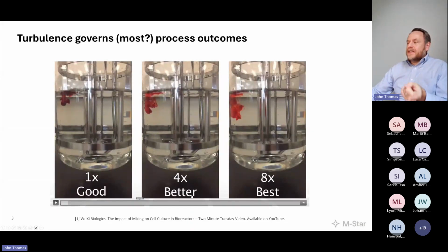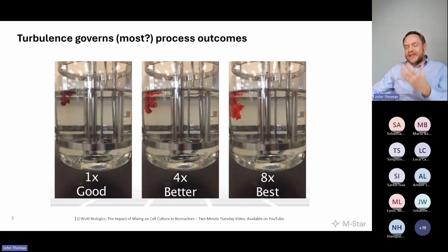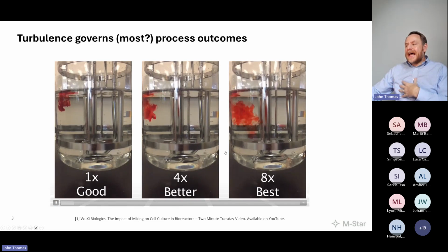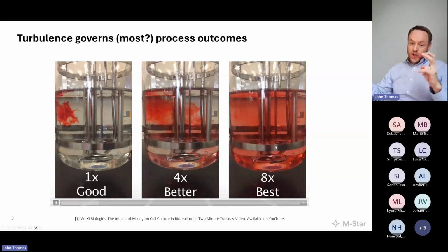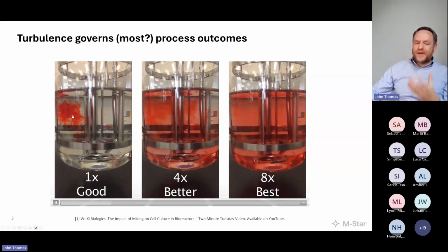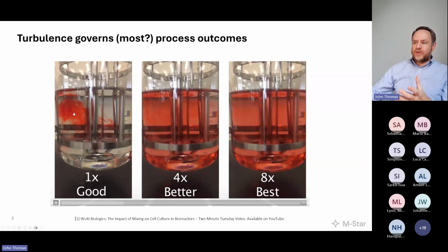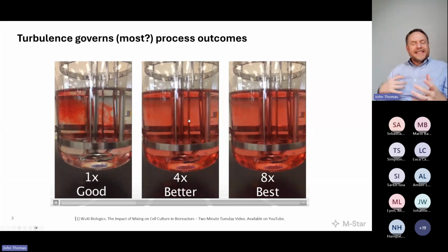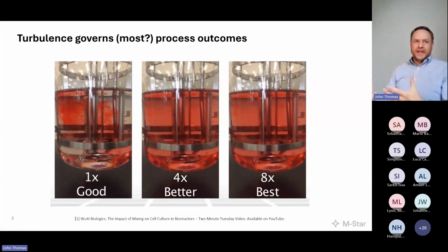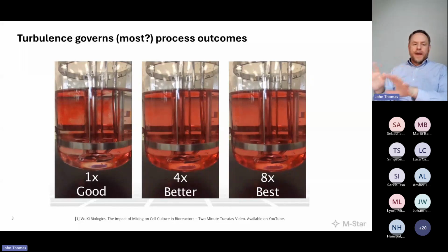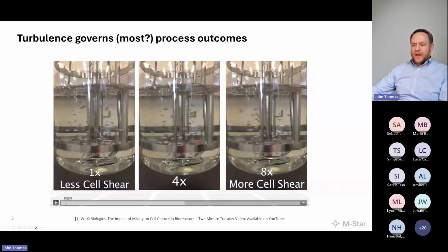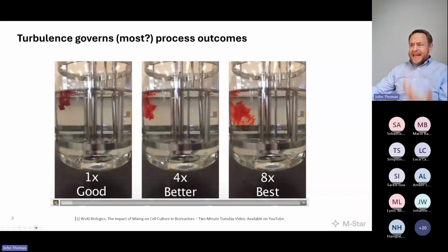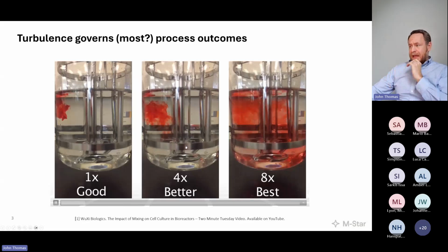But what's interesting here is, yes, the faster impeller speed blends faster. What's cool is the self-similarity of the systems, in that the 8 times faster blend time is happening because the impeller is spinning 8 times faster than the good, as it were, but it's the same physics, in terms of the macroscopic integral scale, evolving just 8 times faster. I always get impressed with this self-similarity of turbulence: if you didn't know the time scale or frame rate, you wouldn't know, just looking at the integral scale, what the impeller Reynolds number must have been. So in terms of blending, this has a self-similar behavior.